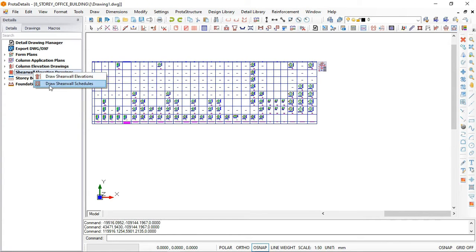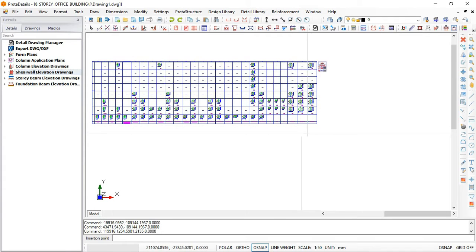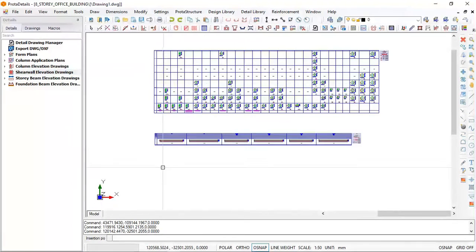So I will just go here and bring out my shear wall schedule also, just to get my numbers of shear walls, typical ones, and also to get the sizes of the rebars, which is the reinforcement that was used to design the shear wall, which we will use for the structural detailing in the Stonebridge company template. Okay, right now you can see our size of shear walls and how they are typical, and the stories which they are typical also.